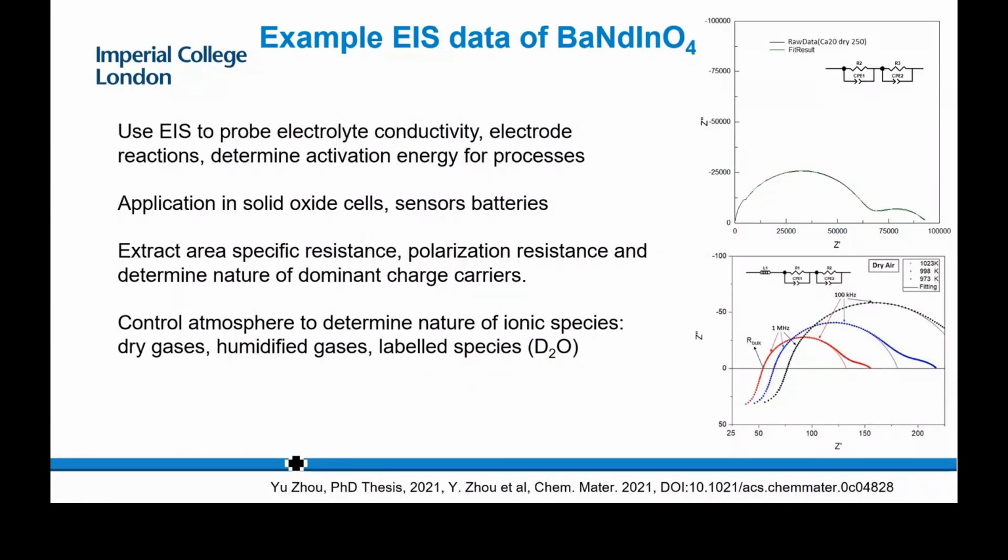So what we're looking at here is an impedance spectrum, from which we can start to extract area-specific resistances. When we're looking at an impedance spectrum, what are we measuring? Well, we're measuring the impedance, and I've been rather sloppy and not included the units here. Typically the impedance spectrum is in ohms. This is the real part of your impedance.